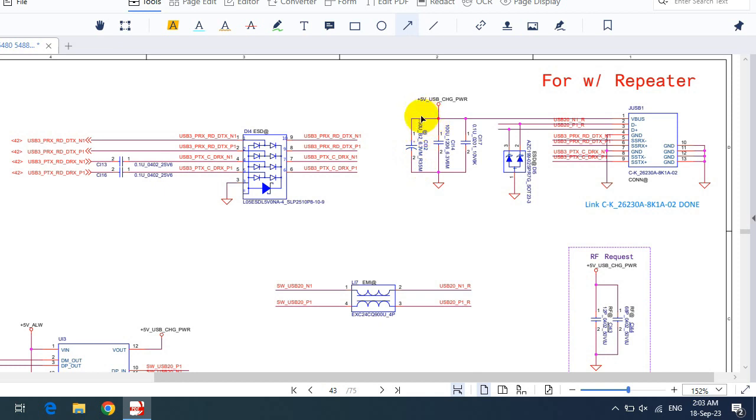So the capacity in microfarad, here we have 150 microfarad, and the voltage 6.3 volts, as you can see. So always the maximum voltage of this capacitor has to be greater than the voltage that we should get. So basically these chemical capacitors or electrolytic capacitors are used to filter the current. This is a filtering component in order to get a continuous voltage.